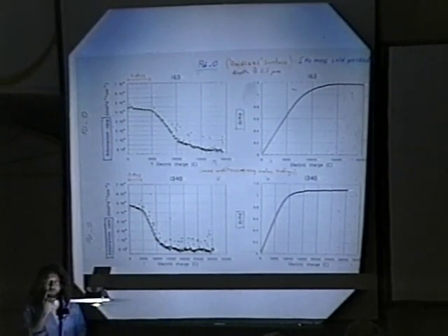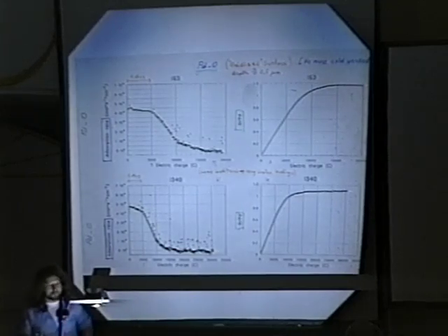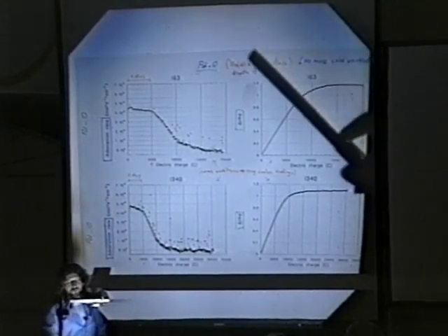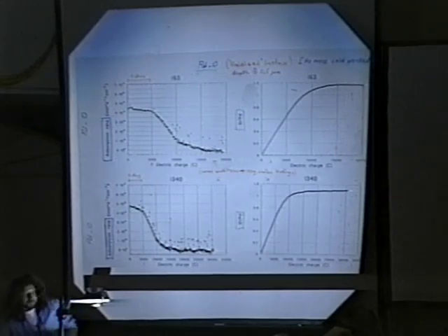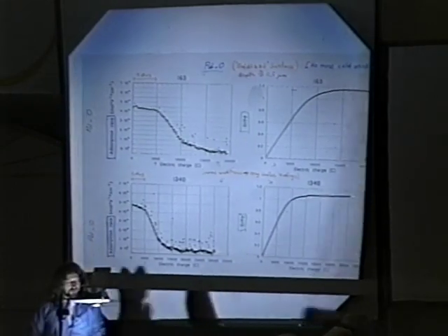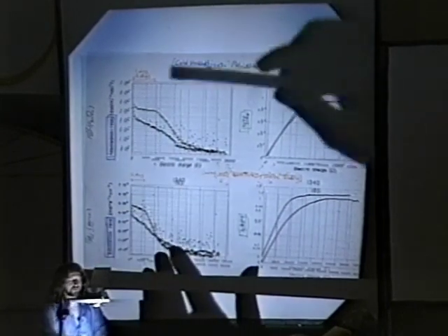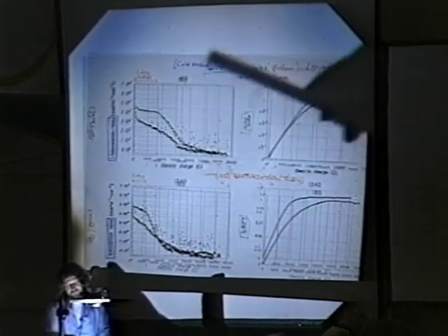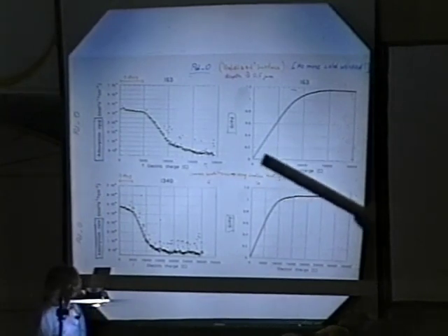Okay. Now we perform a surface treatment on the palladium plate, exactly the same palladium plate from the same batch. All these plates are produced by IMRA, and we just operate some surface treatment. In a special way, we oxidize the surface, and the difference is very sharp looking at the loading rate. So let me show what the difference is. The shape is completely different. The first day, the absorption rate is quite constant and drops down, let me say, quickly. The loading ratio is still very high.